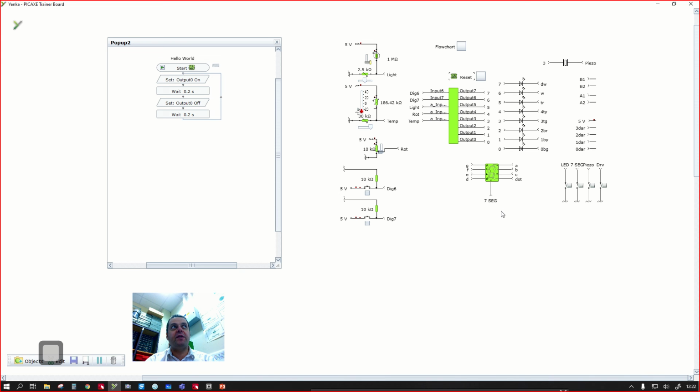As it stands right now, that pin 0 is connected to maybe a few things on here. It's connected to one of the segments on that 7-segment display. It's connected to that light emitting diode. So if those things were switched on, then that light emitting diode would be going on and off every 200 milliseconds. And that's a really nice lead-in to how good microcontrollers are and what they do that we can't do. That microcontroller could switch that pin on and off exactly every 200 milliseconds.